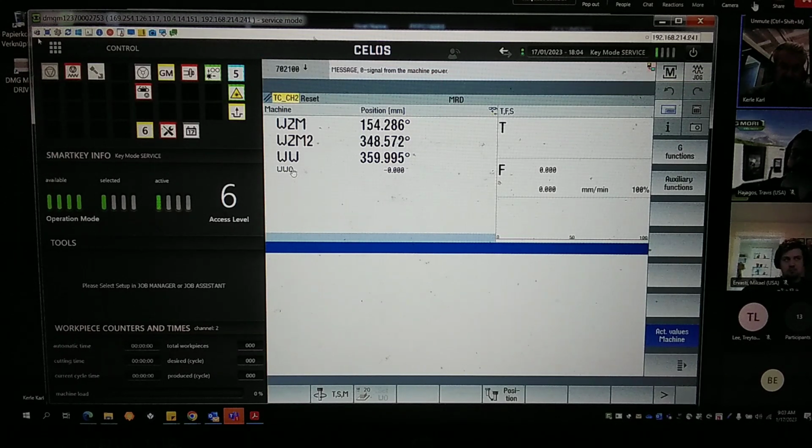I don't know if you know that, or you have a little bit more experience with Siemens. If not, I will tell you shortly. Let's say the NCU we use on that machine, the designation of this NCU is 730.3. That means this is the latest, the most powerful NCU we can have at the moment. So that also means for this NCU, it is possible to control a maximum number of axes. 31 is the maximum number of axes that could be controlled by this unit, but